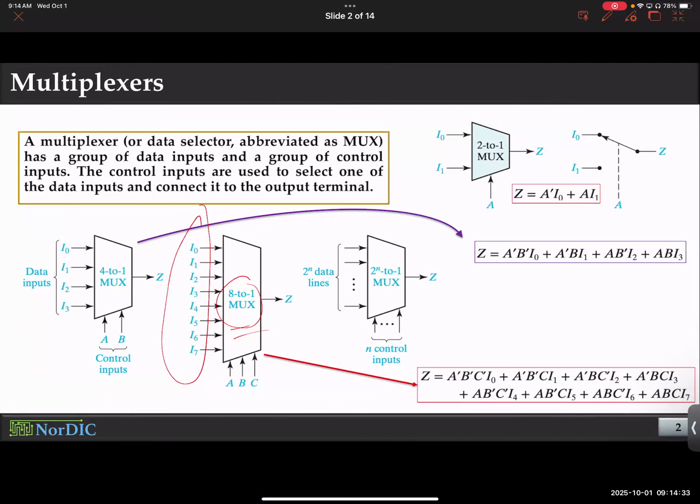All right, and hopefully, with the ideas that we have gone through so far about multi-stage circuits and multi-input circuits, you will appreciate the difference between the two. In terms of Boolean logic, they're basically the same. If you implement an 8 to 1 mux operation with two 4 to 1 muxes, it should be the same in terms of functionality as an 8 to 1 implemented directly. But in terms of hardware performance, it will definitely be different.